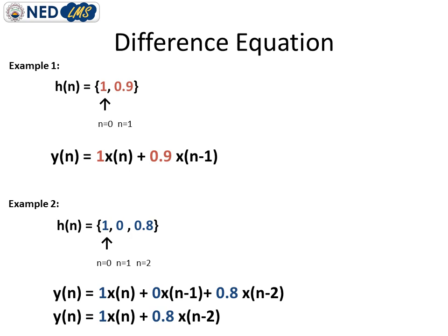In example 2, you can see we have three system coefficients, with the indices starting at the first coefficient. So we can write the standard difference equation for this impulse response. y of n is equal to 1 coefficient attached with 0 delay, 0 coefficient attached with 1 delay, and for the second delay a 0.8 coefficient is attached.